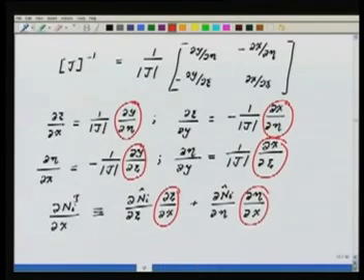In this case, you notice that for these triangles, with linear mapping, del psi del x, del y del eta, del x del eta, del y del psi, del x del psi are all constants. Why? Because x and y were linear in terms of psi, eta. Take the derivative of the linear, you will get a constant. Because they are all constant, the Jacobian is also a constant.